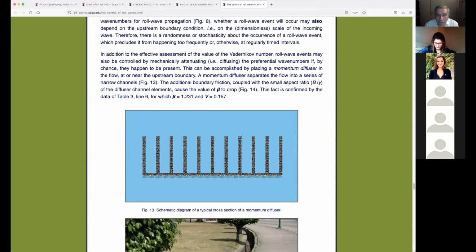So we came up with what we call a diffuser. Since I already mentioned to you that the deep channel would produce diffusion, then instead of making one channel rectangular, we would make 2, 4, 6, 8, 10 channels which are deep. Each one of them is deep. And we do believe that will diffuse at the entrance. If it's placed at the entrance, it will diffuse all the bad waves that want to become amplified waves downstream. They will be diffused completely. So this is what we call a diffuser.